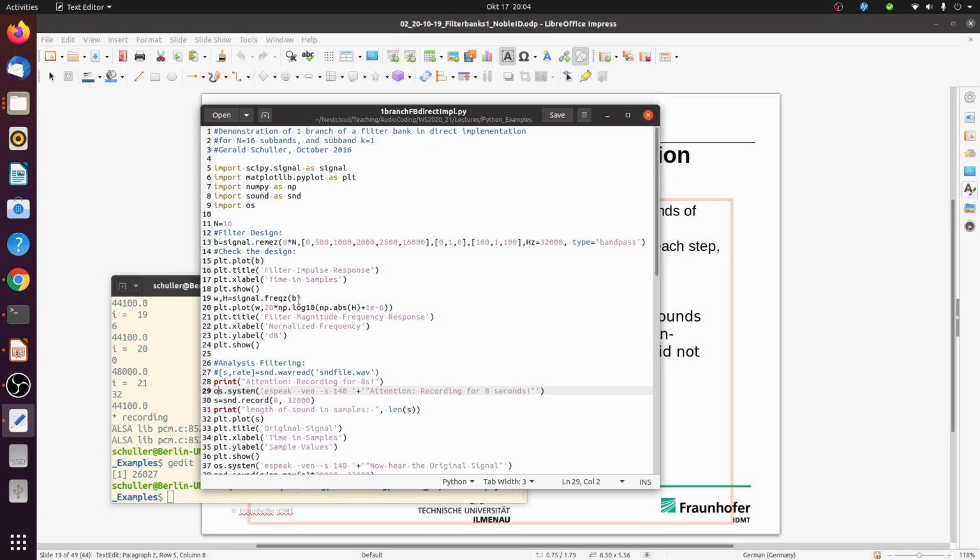So basically it takes the impulse response in the time domain, appends zeros to fill out usually 512 or 1024 samples to have like a long block of samples, and then it applies an FFT to it. And then you get the frequency response, capital H. So H is a complex valued frequency response, and W contains the frequency samples at which the H coefficients are computed.